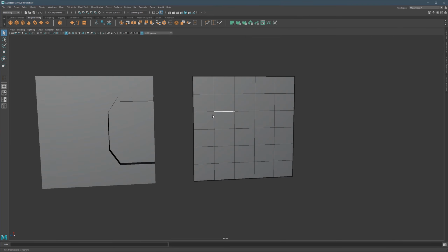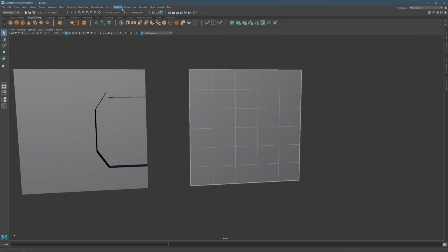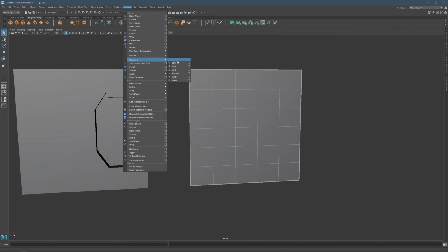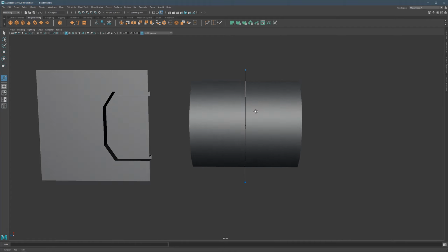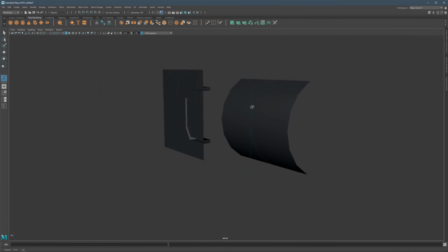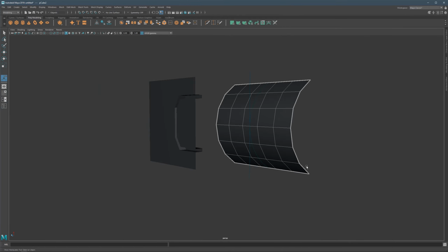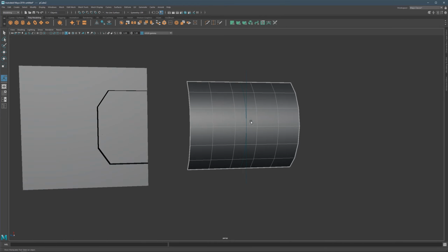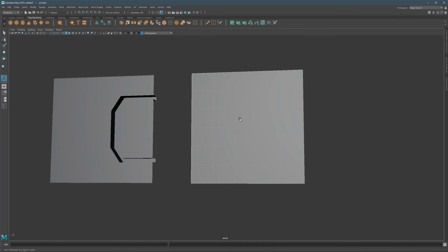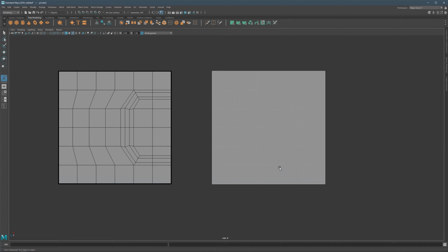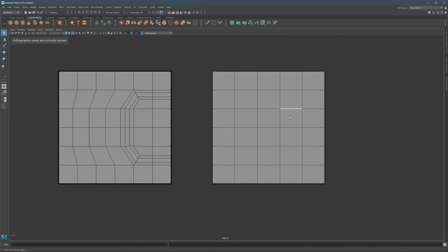If we come here and apply the same deformer, nonlinear, bend, now it will bend properly. We haven't touched any of the structural edges, and we just removed the ones that were problematic and then brought them back in a proper way. Now that we have that, we can focus in the same way like we did before.